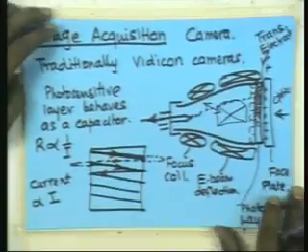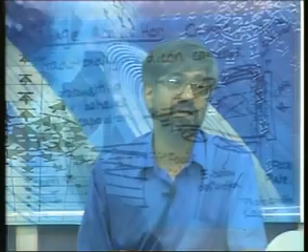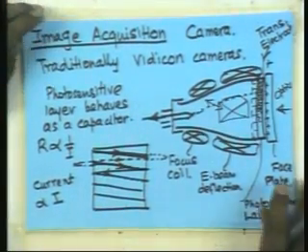I thought there were separate beams for each location. No, it is a single beam, controlled by the deflection electronics. It scans through the entire area by horizontal lines, and each time is shifted down by a small amount. So you get a number of lines, and for each line, the current flowing gives us the intensity corresponding to that particular point. This is done by the electronic deflection. Then you know the CRO and that principle; it's basically similar. There you are generating an image, here we are trying to capture the image.